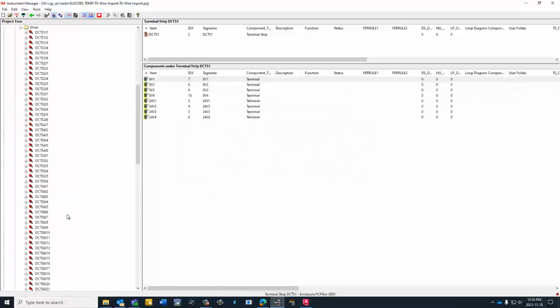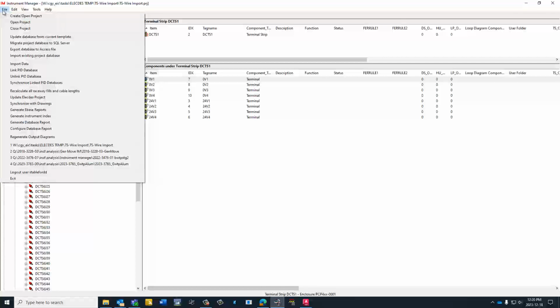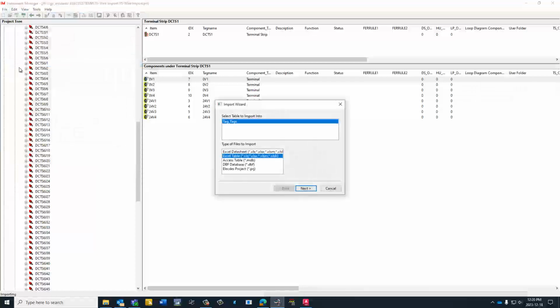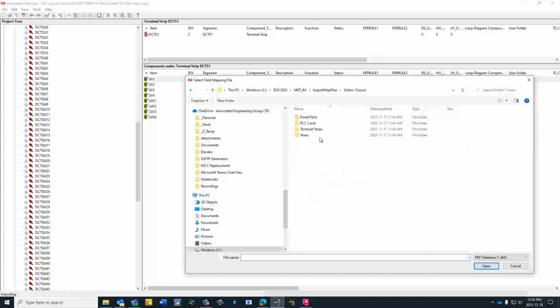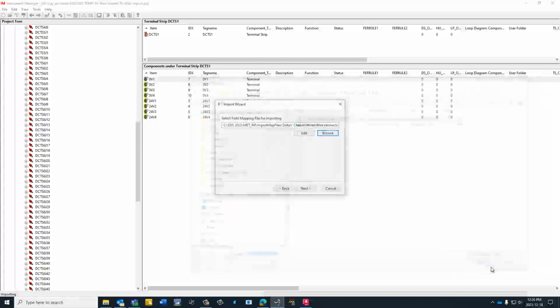Do I want to see what we have? We now have a heap of wires that we've added in. See, there's a reasonable amount there. Now we're going to connect those up because I've already provided some connections in the source mapping file. So we do the same thing. File, import data, table. Going to pick the correct mapping file, and I want the wire connection map this time.